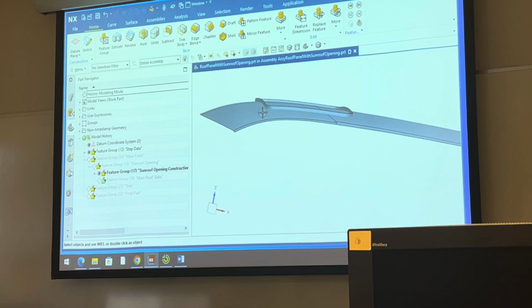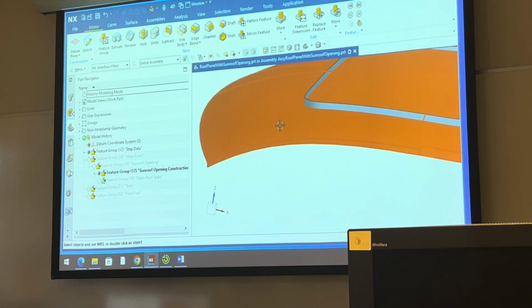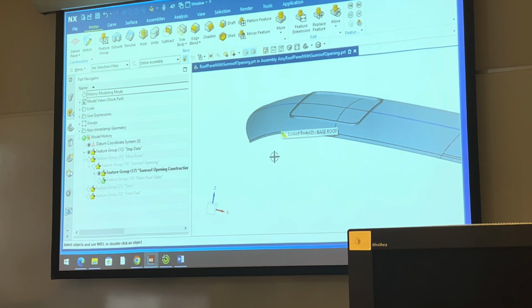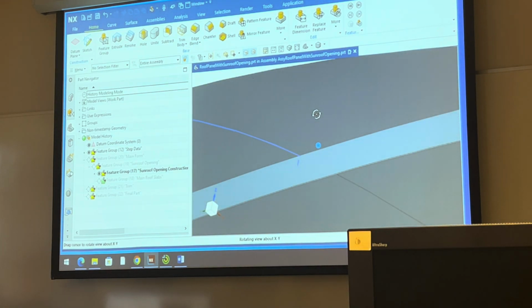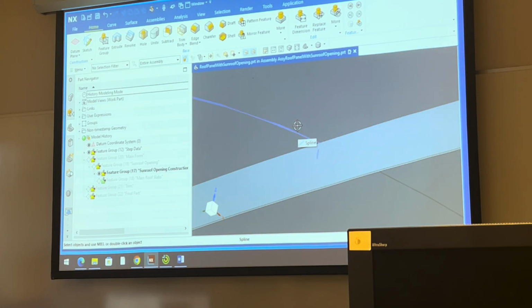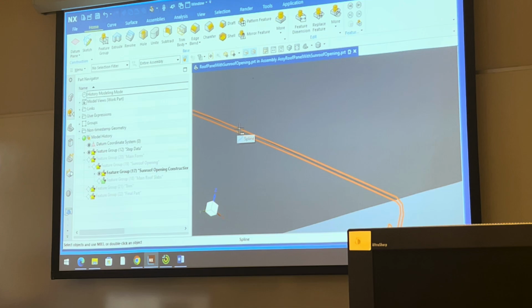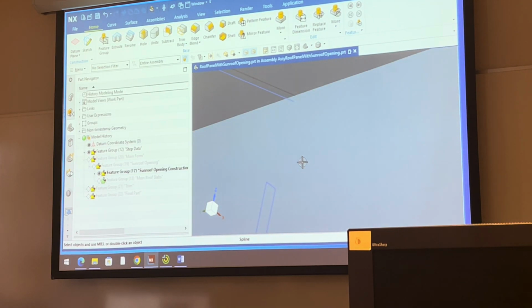Make it active. And I really haven't talked about what we're doing in this file, but we're going to first offset this smoother linked surface downward by the roof panel material thickness. Right? It goes back to that concept, if you look at the section curves, there's two curves there, it's kind of hard to see. But there's the top curve and the bottom curve, it's easier to see it that way. We're designing the lower part of it, we're doing sheet bodies, surfaces. We're only doing one side of the material. So logically, we're doing the bottom here as we come around the bend, right?